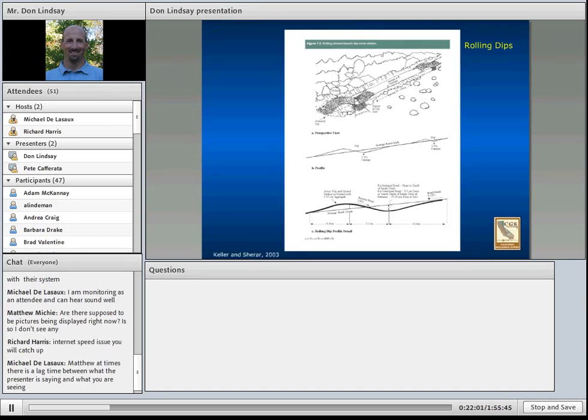Rolling dips are referred to as broad-based structures used in moderately traveled roads. Relative to water bars, the profile or cross-section of rolling dips have a relatively low amplitude and a long wavelength, as you can see in the diagram. Where necessary, the wetted perimeter of an outlet of the dip should be armored.